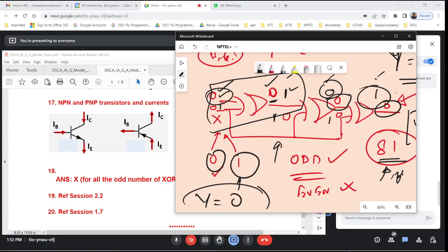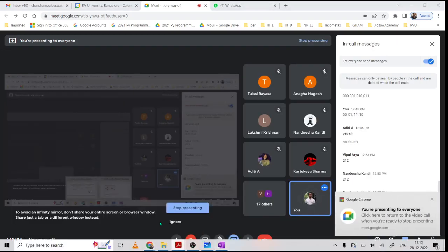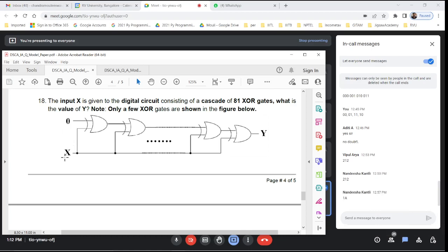So there could be different combinations. I want you to try it out yourself and understand exactly. What you are supposed to do is, if we give any variable, you have to assume that it could take any two values, 0 or 1, and then understand the circuits, what will happen to the output, and express that output. Maybe you can create a truth table and then see for different combinations of input what is the output, then write the equation. It could be a 0 or 1, or it could be same as x, or it will be x prime also. It could be a complement of x.